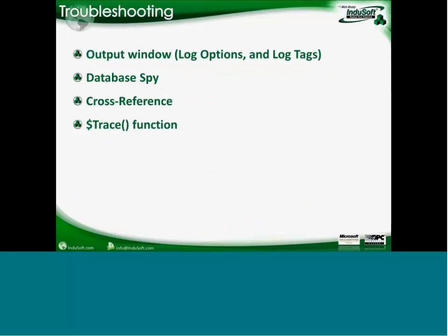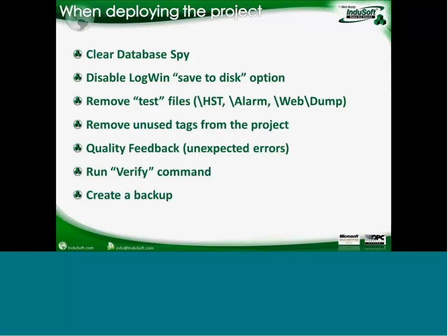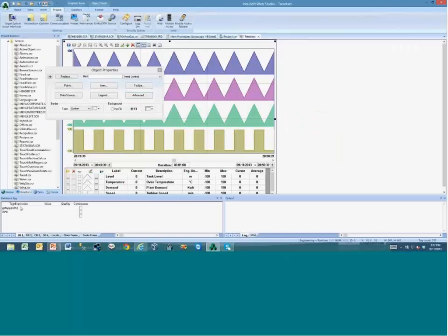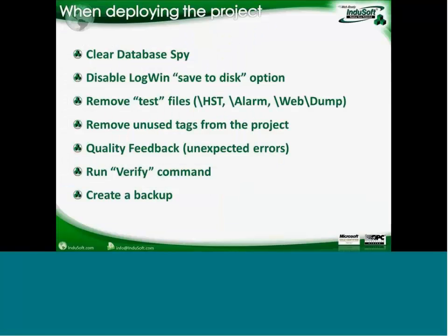InduSoft offers several troubleshooting tools that should be used during the tests of the application. And when you are done with the application, we recommend clearing the database files. So if you have any tags or expressions here, you can delete them from all the tabs, clear all the expressions from here. Disable the option Save to Disk from LogWin to make sure it does not keep saving logs. Delete the history files from the HST, ALARM, and the log files from the WebDump subfolder to have an application clear of history data.